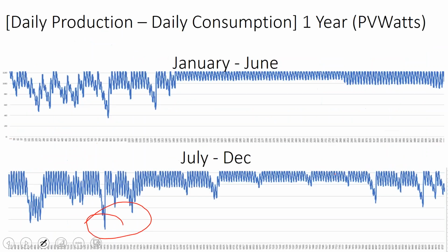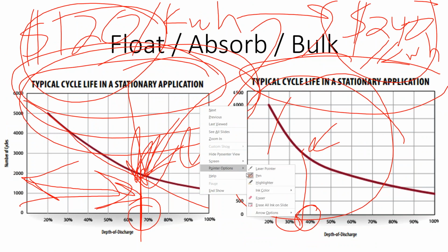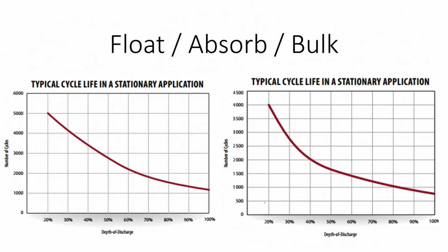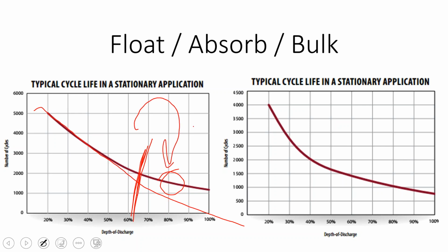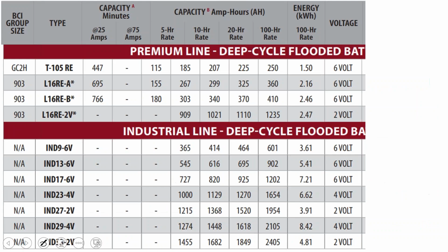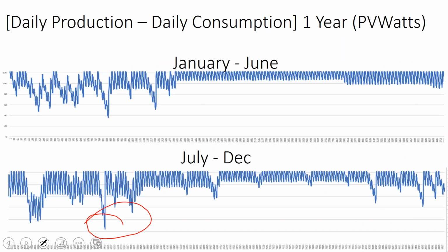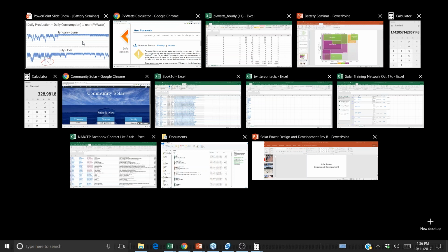And so when we go and look at it, we went with an industrial forklift battery. And we said, well, you know what? We can once a year take this industrial battery that's really designed for a 65% depth of discharge. And if it happened to go down to 80% for one day out of the entire year, you know, we're not getting down to this 80%.